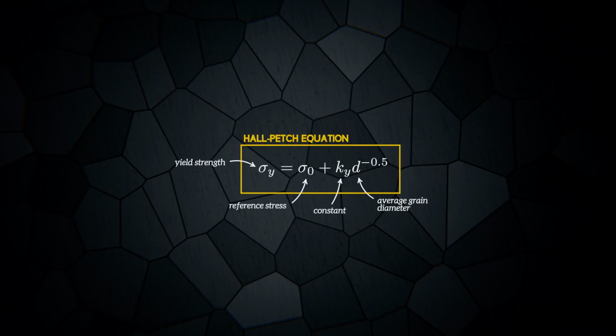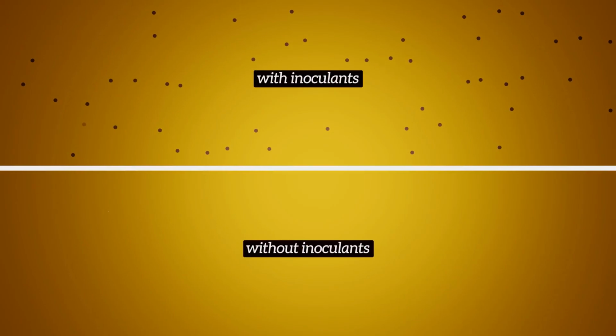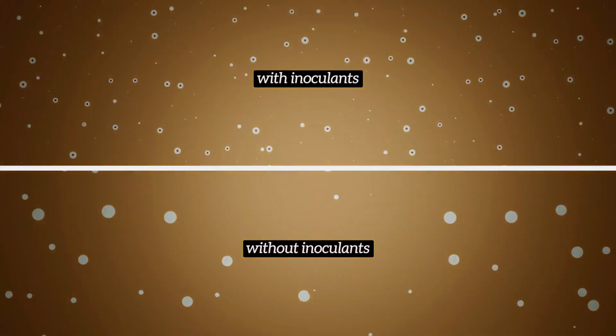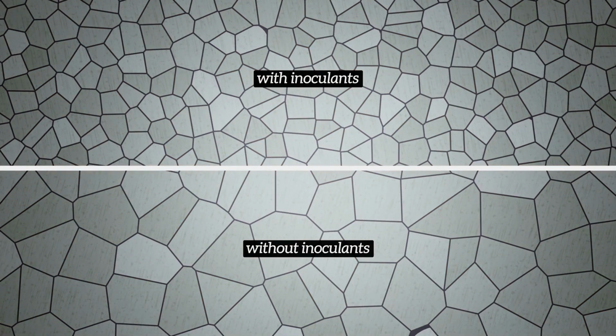We can use this information to intentionally strengthen metals by controlling the size of the grains that form as the metal is cooled. Impurities called inoculants can intentionally be added to the molten metal so that crystal nucleation occurs at more sites than it otherwise would have, leading to smaller grain sizes.